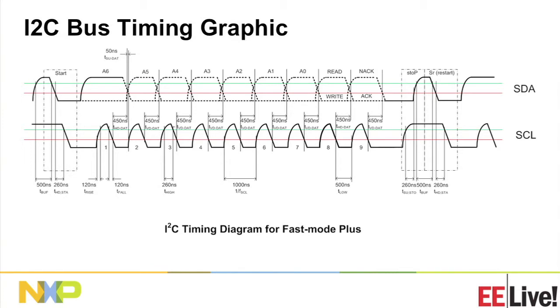And when we do that, we lose backwards compatibility. We also lose some of the nice features of the bus, such as the wired-OR collision avoidance, and the fact that there's an acknowledge bit every 9th bit to confirm that the data has been received. Don't forget, this is all 1980s technology, and it's all 2 wires, 2 resistors. It's very unlikely we could simplify it.